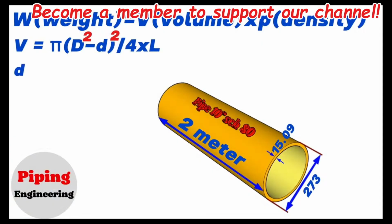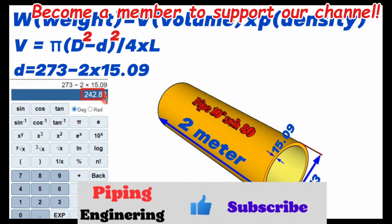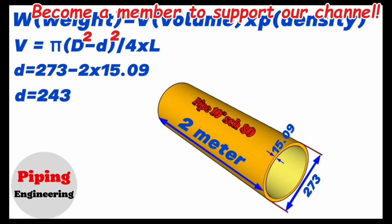Now we can calculate the inside diameter of this 10-inch pipe. The inside diameter equals the outside diameter 273 minus 2 times the wall thickness 15.09. Using the calculator, we find that 273 minus 2 times 15.09 equals approximately 243. So, we found that the inside diameter of the 10-inch schedule 80 pipe in our example equals 243 millimeters.